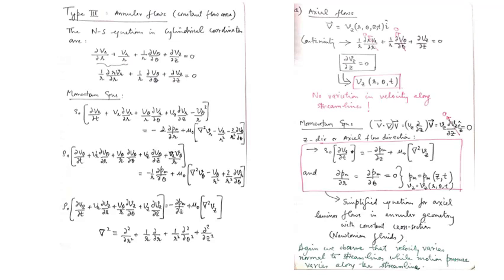Now coming to momentum equations. So we always examine the convective term first in the hope that if it comes out to be 0, then we are very happy because the nonlinear term of the Navier-Stokes equation is gone out of the window. So V dot del V is Vz ∂/∂z V, and again the unit vector ez is not going to vary with z.